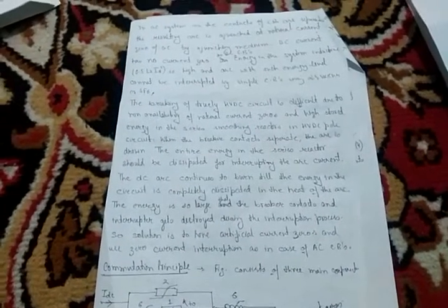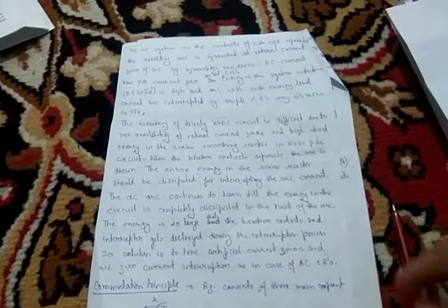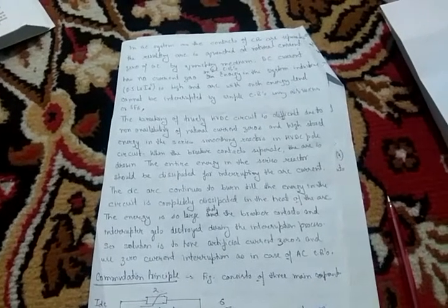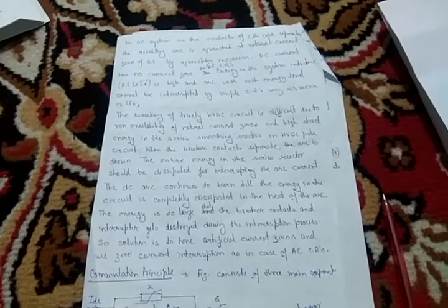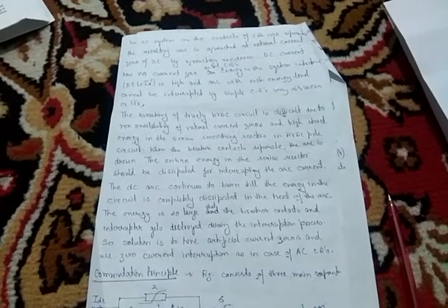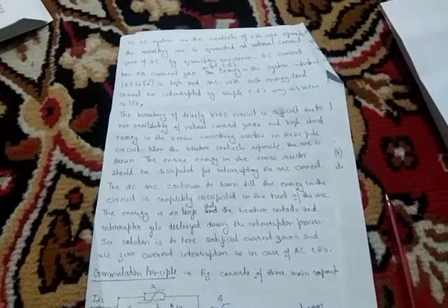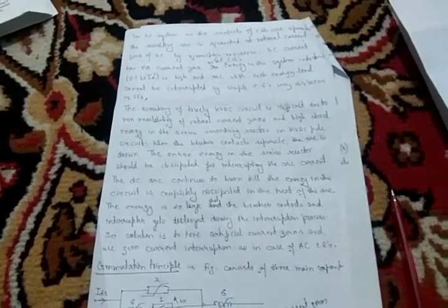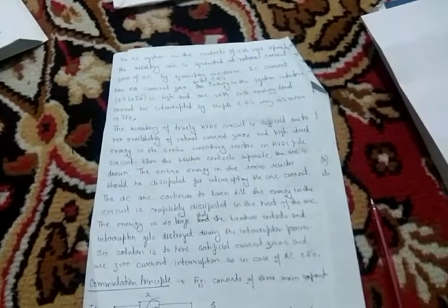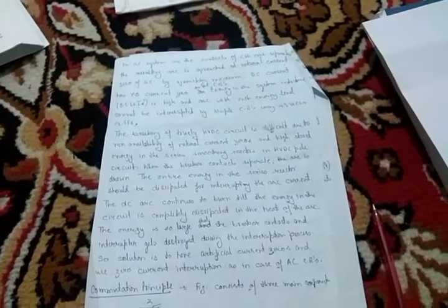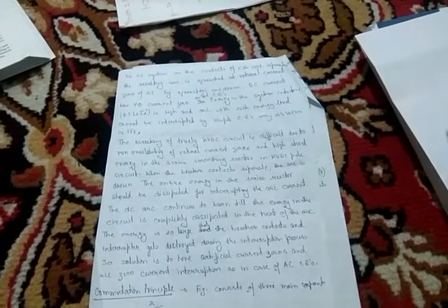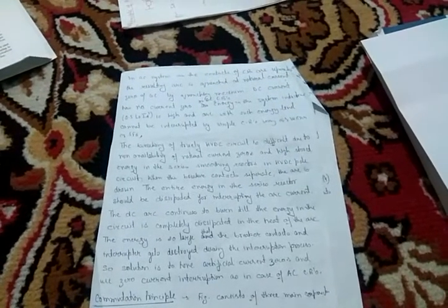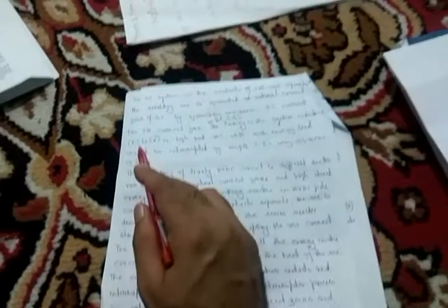So you know that in case of AC, the contacts of the circuit breaker are separated from each other. As they are separated, an arc is developed, and this arc is quenched by the arc quenching medium like SF6 or vacuum circuit breaker when the current passes through the zero point, which is called the natural current zero point of the system. However, in a DC circuit breaker, there is no zero current. And also in DC, the energy in the system inductance is high, which is given by 0.5 L into I square.